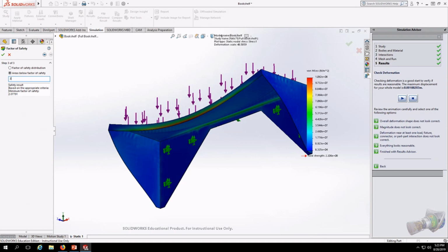A higher factor of safety allows for the forces you expect something to experience to be exceeded without having the part fail, so it is particularly important for things that experience natural disasters or are at risk of being subject to forces beyond recommended limits. However, a high factor of safety often means that more material is being used than needed, and this could add to manufacturing costs and part mass, which is one of the primary reasons that factor of safety in aerospace applications is often fairly close to 2.